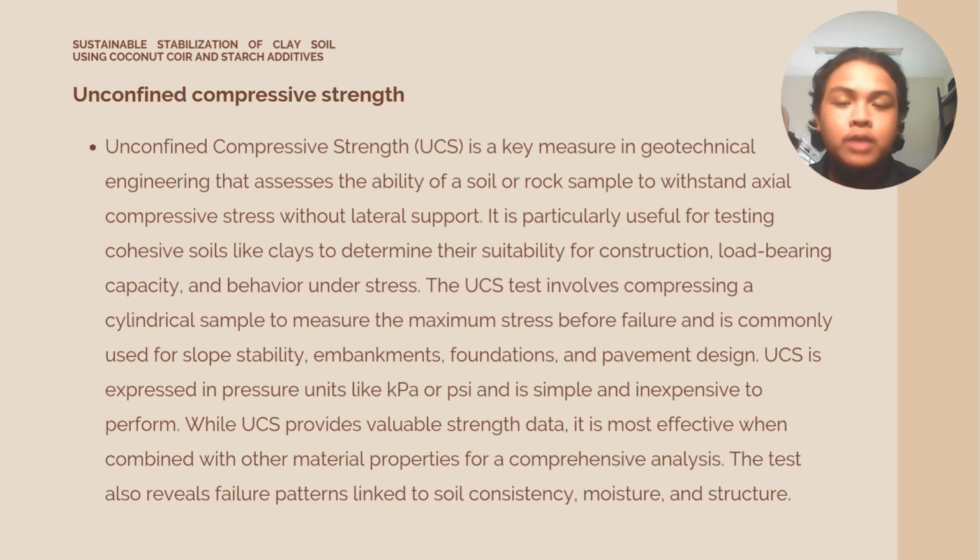Now we're moving to the last part of chapter 2. Unconfined compressive strength. Unconfined compressive strength is a key measure in geotechnical engineering that assesses the ability of a soil or rock sample to withstand axial compressive stress without lateral support. It is particularly useful for testing cohesive soil, like clay, to determine its suitability for construction, load-bearing capacity, and behavior under stress.